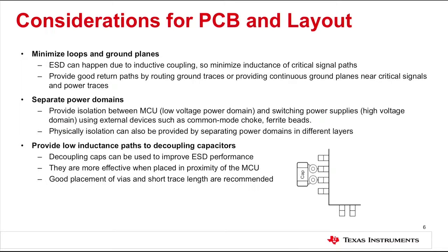It is also recommended to separate power domains by providing isolations between MCU and switching power supplies using components such as ferrite beads, common mode chokes, etc. Whenever possible, physical isolation can be provided by separating power domains in different layers. You can use decoupling caps to improve the ESD performance, but you should keep in mind that they are more effective when placed in close proximity of the microcontroller pins. This is illustrated in the figure shown on the screen.